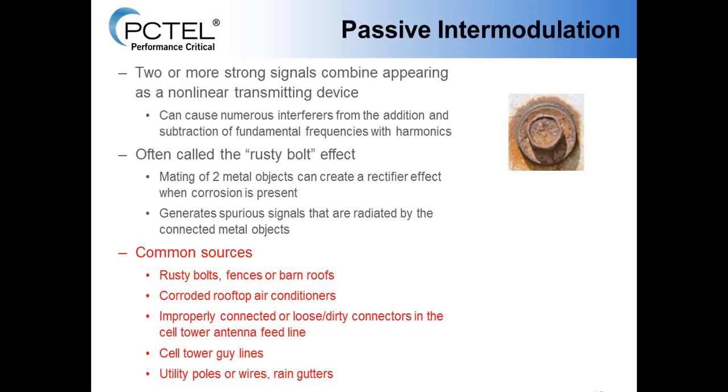So you have to be very careful where that antenna is placed, because if it is placed near some metal ductwork or some I-beam girders, you can actually get PIM created by the signal being transmitted into that metal girder or ductwork, and then combining to cause all these different frequencies and harmonics of these frequencies that cause passive interference. So it's actually starting to become a larger problem on these in-building systems than it is even on the macro cells that we have today.